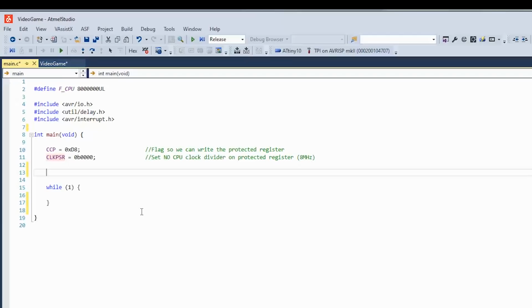So the first thing we want to do is set our data direction register B, which is port B. We can write this out in bits. So 1, 2, 3, 4. The top 4 bits of that do nothing. Oh, I'm sorry, 3, 2, 1, 0. Okay, so that would set PB1 as output.